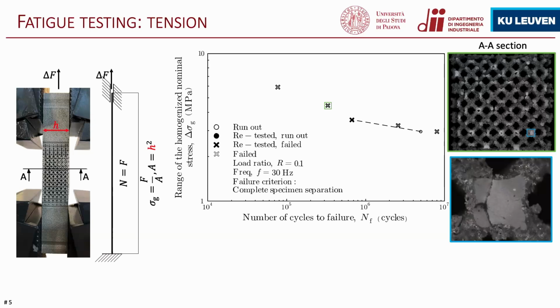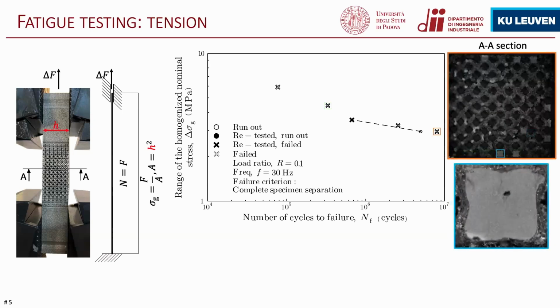And it's very interesting to note that we have multiple crack planes initiating from each of the corners. And that is suggesting that probably it's behaving like a notched material rather than a defective material. Again, I'm plotting now the fracture surface of this specimen.